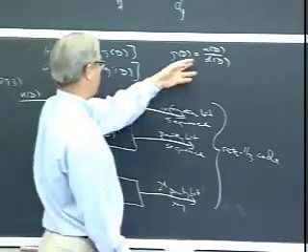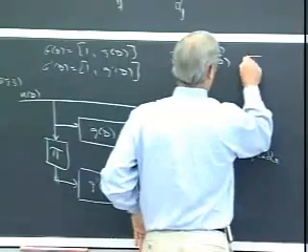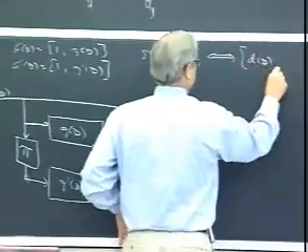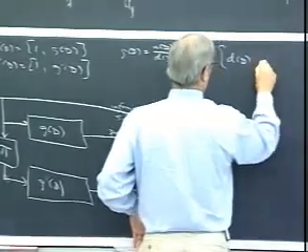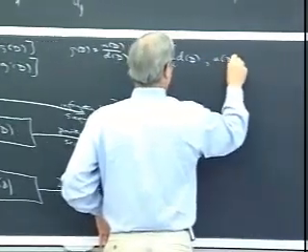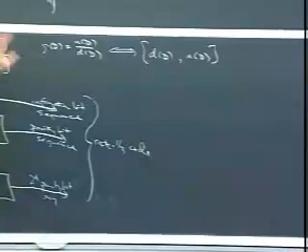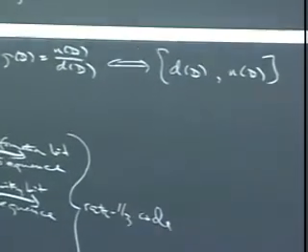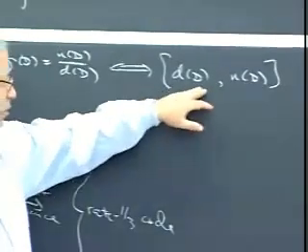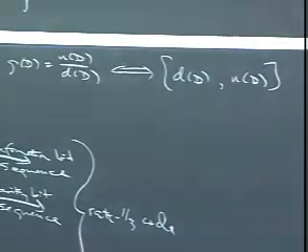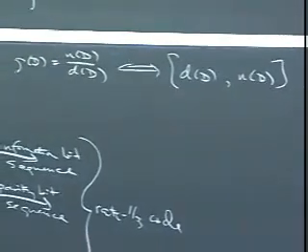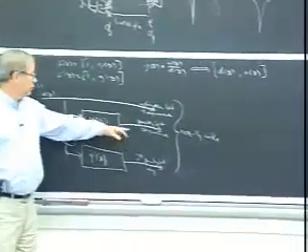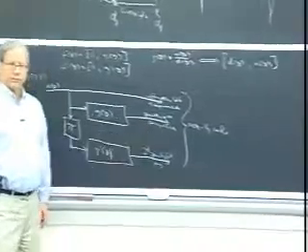You know, if you have N of D over D of D, this is going to be equivalent to the non-recursive feedback-free code, which is D of D, N of D, right? We worked all that out. It's equivalent to the code where you multiply through by the denominator. And so you get the same code with D of D, N of D, but you don't want to do that because you are concerned here about the input-output relationship between input bits and the encoded bits.